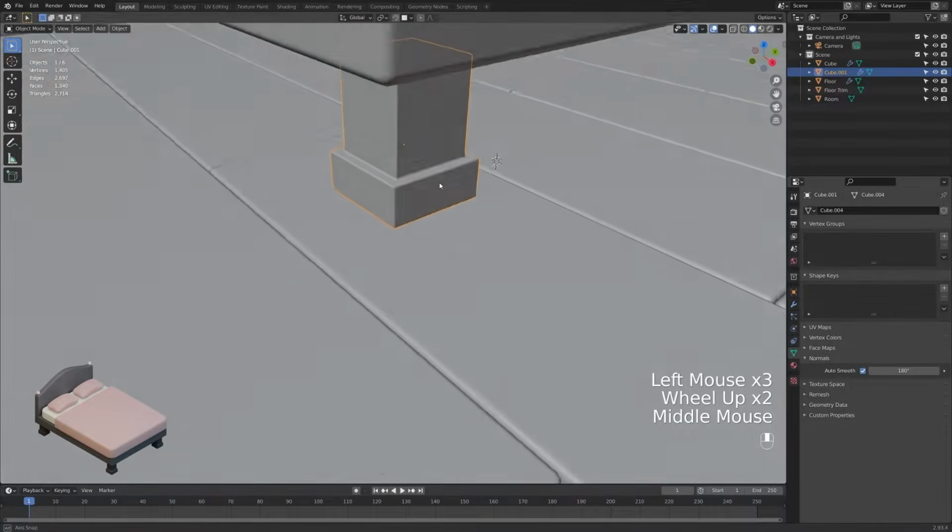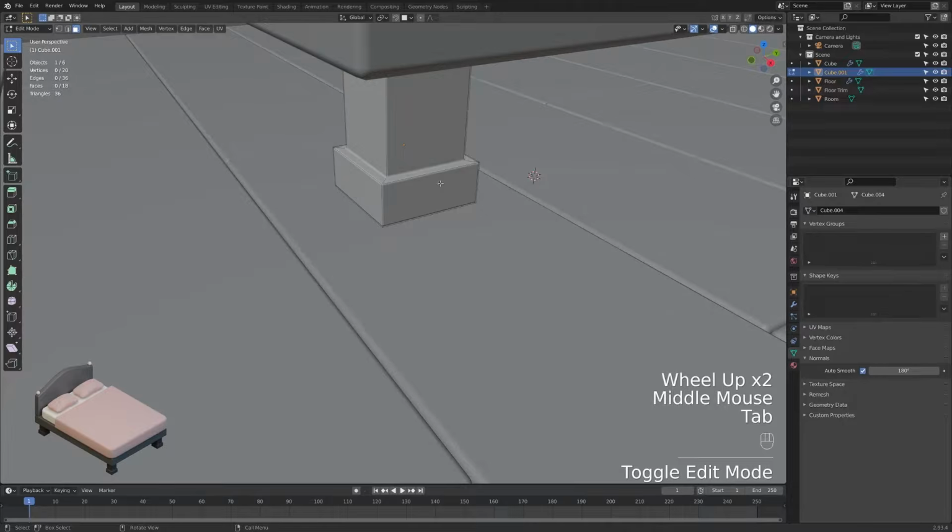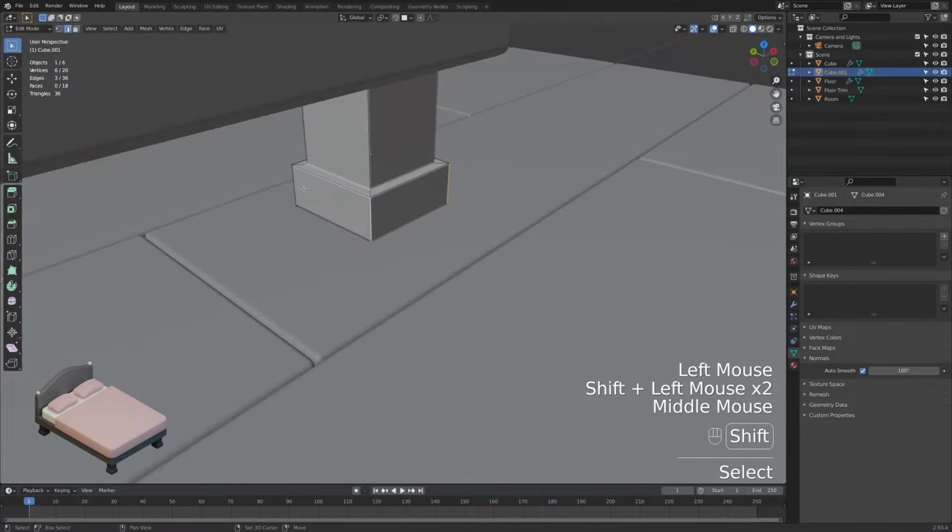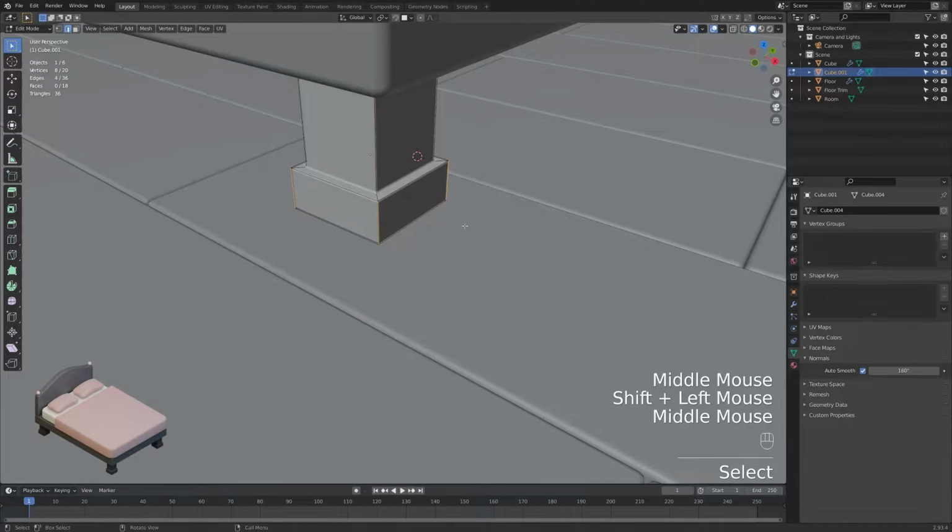The corners of the base look like it would be very painful to smash your pinky toe against, so I'm going to round them out a bit by adding another bevel. Select the 4 edges and hit Ctrl B to create a bevel.